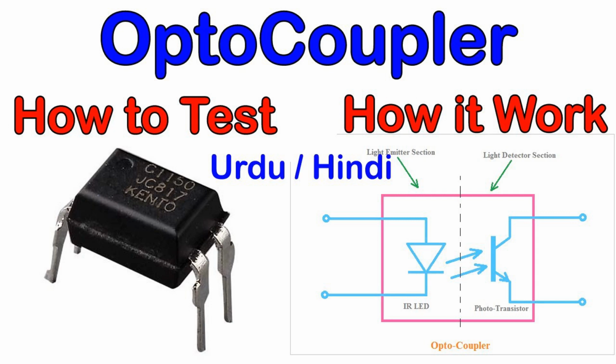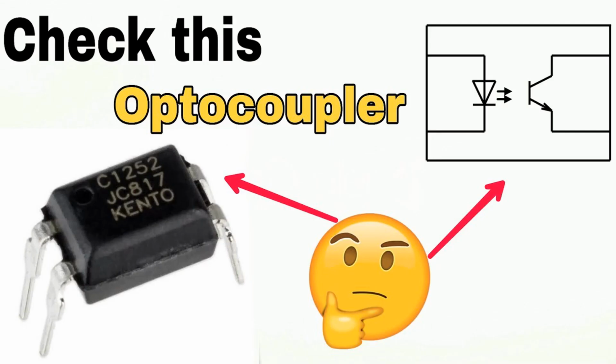Signal conditioning may involve the use of low-pass, high-pass, band-pass, or notch filters to shape the frequency response of a signal. Impedance matching. When connecting two components with different impedance levels, signal conditioning can include impedance matching to ensure efficient power transfer and minimize signal reflections. Transformers and matching networks are often used for this purpose.